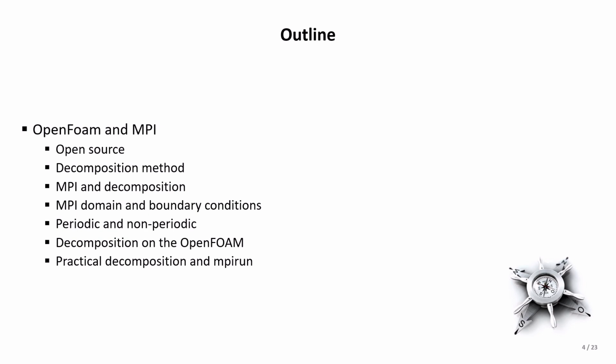OpenFOAM is open source software. It's used in the fluid dynamics area, and since it's free and open source, we can make a new design of the problem with the domain and the boundary conditions, write a new problem, and also write a solver for it and make modifications to use with high performance computing.